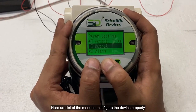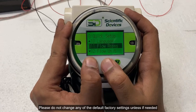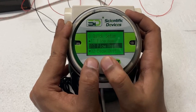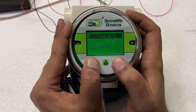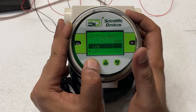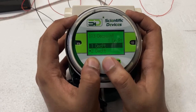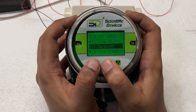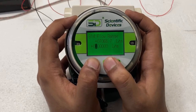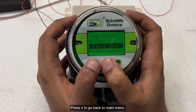Here are list of the menu to configure the device properly. Please do not change any of the default factory settings unless if needed. In quick settings you can change the device response time, its flow units, number of decimal places to show, its flow range, long presses M key to save the new value. Press Z to go back to main menu.